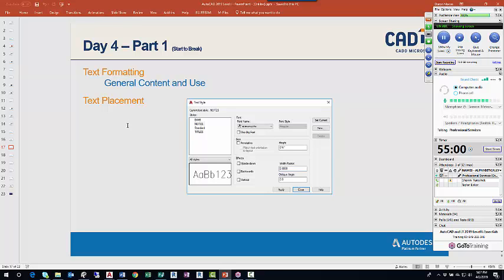It would be either 1/8 inch or 3/32 of an inch, and at the end of the day we came to set our text height to 6 inches in model space, which, when we print at 3/16 of an inch equals 1 foot, will look 3/32 of an inch high, which is a nice height for legibility, but it won't overpower or clutter the drawing. So we created some text, we placed some text, and that's where we are to this point. Questions on anything at all so far?